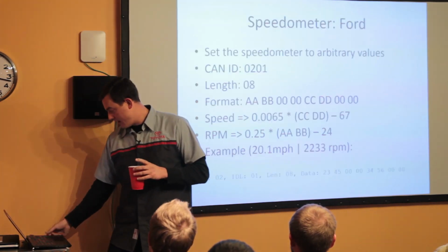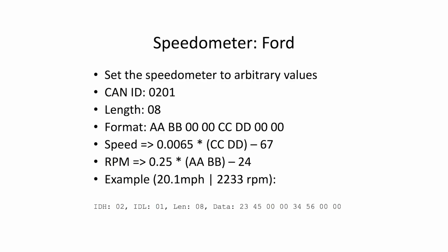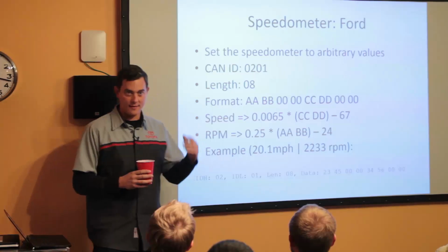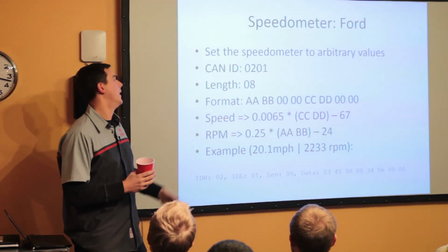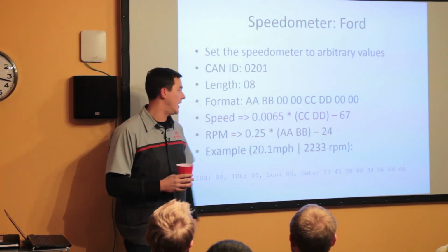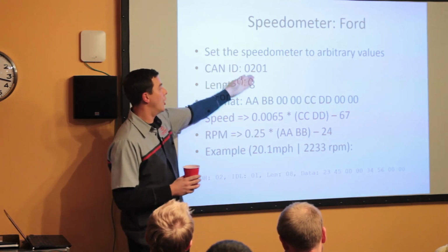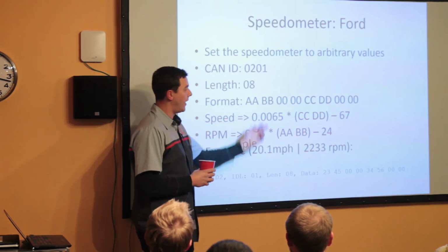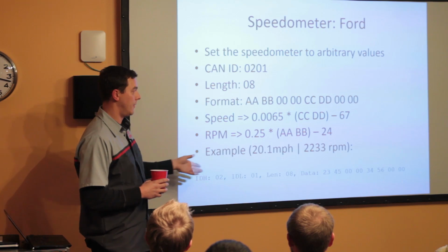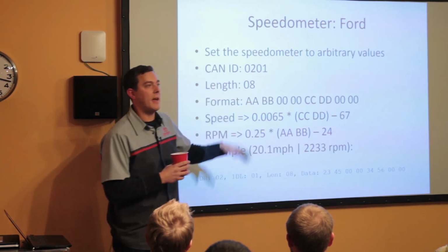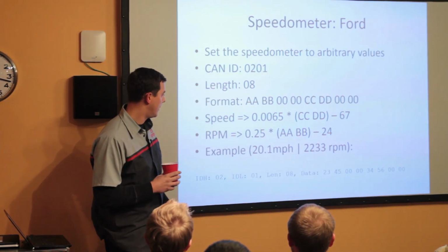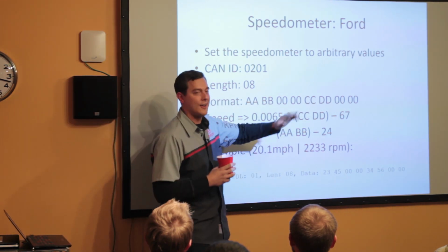So how do these work, right? For example, we decoded, when I was doing IPS, IDS at ISS Force, we call this a decode. We figured out the proprietary message scheme. For the CAN ID 0201 in a Ford, these 2 bytes equate to the speed in RPM. Do some math. Charlie does math. He has a PhD in math. I let him do all the math. And in the example, you can get speed in RPMs, right?